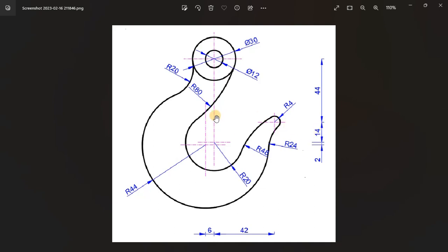Each time you use the line tool and type a distance, it creates an endpoint, and then you type another distance for another endpoint, and so on. That's why I don't need to measure, I just follow the endpoint. At that endpoint, I'm going to draw a line coming here, a distance of 42, and then we also make a cross there.